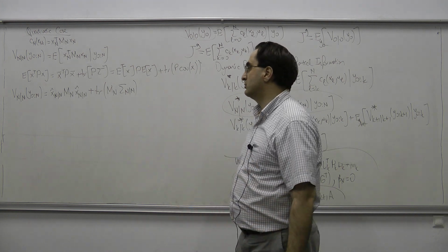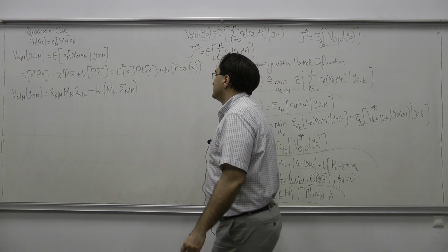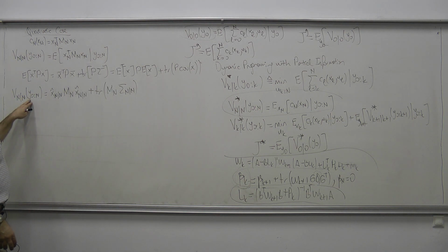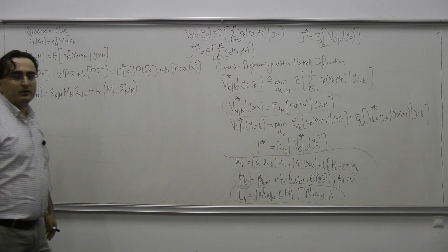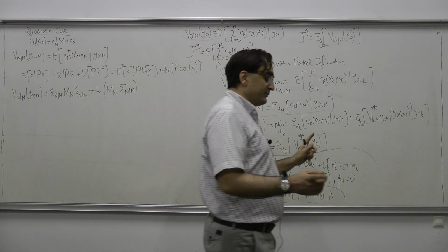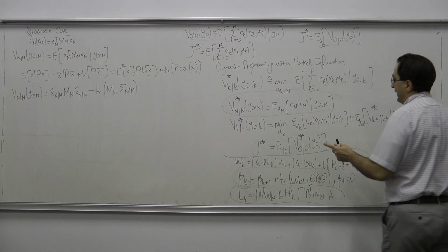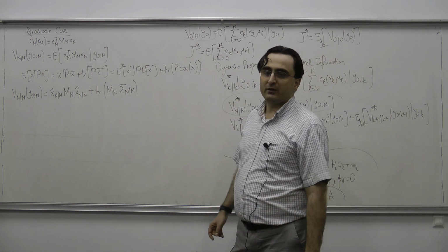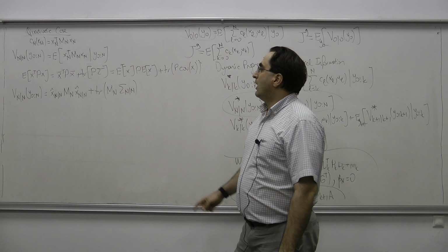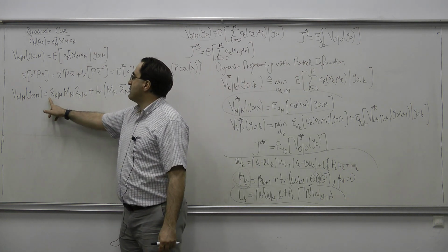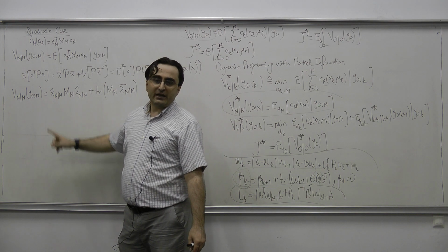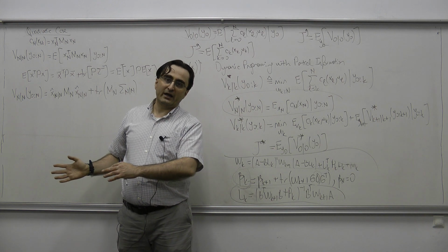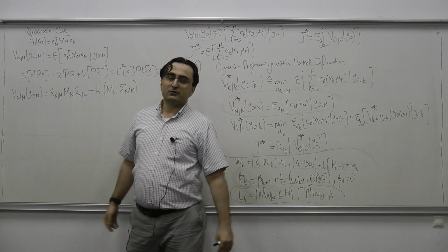We are going to be going backwards. So then this cost to go should be a function of y0n. Cost to go is a function of y0n. Where is y0n on the right hand side here? I know that these estimates, x hat n given n, are a function of the measurements from y0 to yn by the Kalman filter recursion.